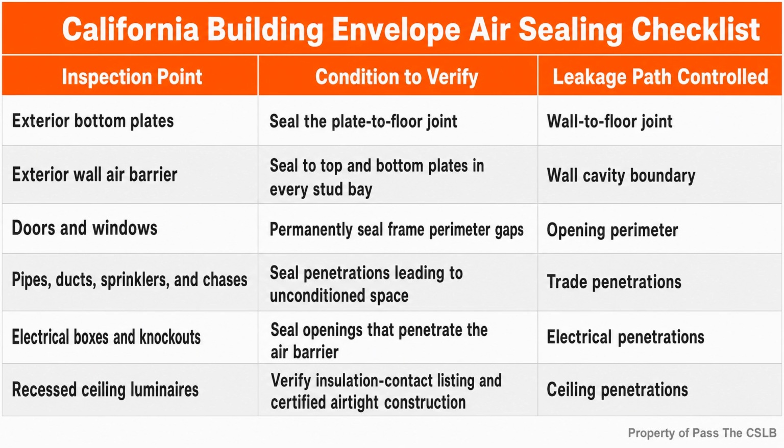California energy requirements call for potential leakage sources at joints, penetrations, and other envelope openings to be caulked, gasketed, weather-stripped, or otherwise sealed. The exact suitable material depends on the assembly, the opening, the approved details, and any fire or listing requirements. The supervisory principle remains constant. The finished seal has to restore the boundary.